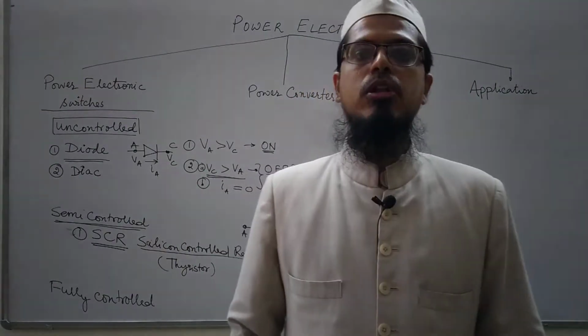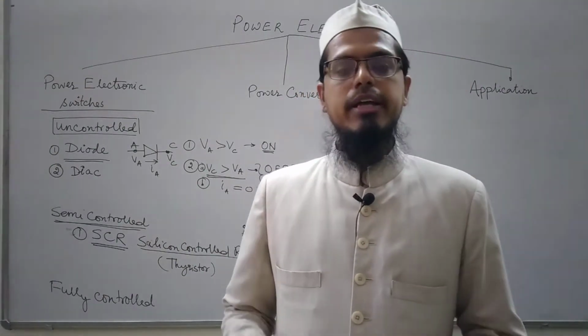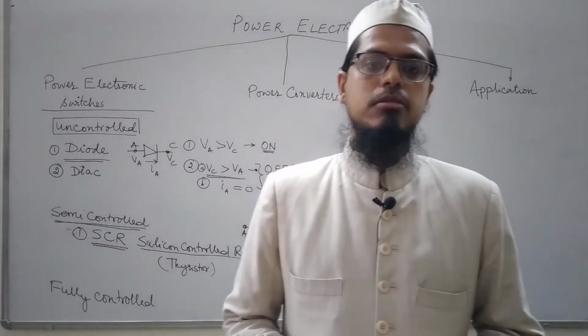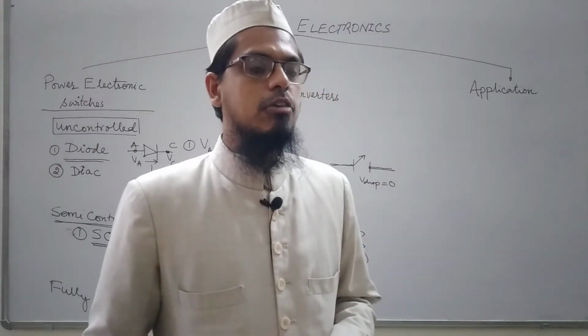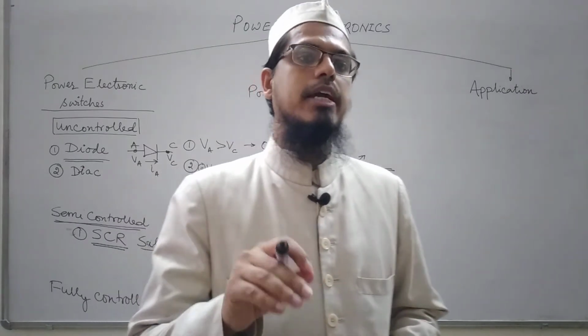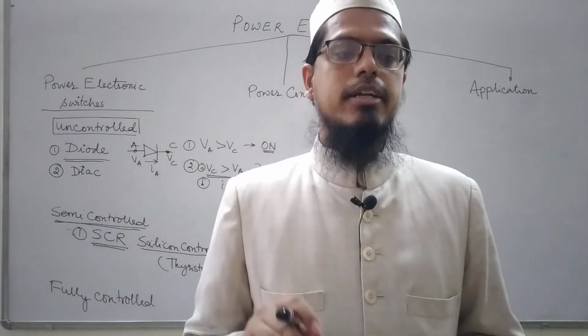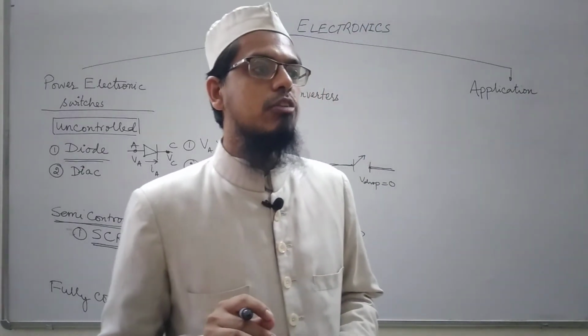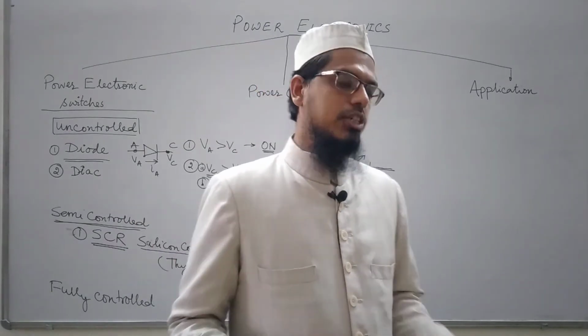So that is why we call SCR a semi-controlled device, because we can turn it on whenever we want by supplying a gate pulse, gate current, but turning it off depends on the circuit condition. Fine.